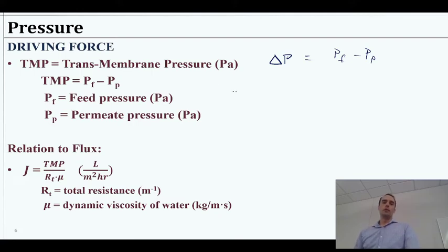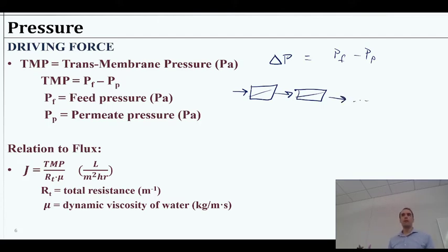It's worth noting that you can have systems where you feed into some membrane that goes into a second membrane and so on. You can drive all of that with a pressure at the very front, and each of these membranes will cause their own little pressure drop. So you could have sequential pressure drops, and any one membrane is only providing some amount of resistance. And then you have the series. Of course, you could add a pump to pressurize further in the middle or whatever.